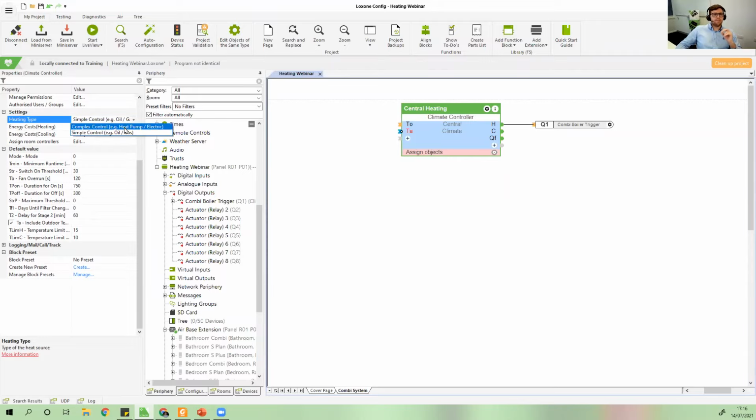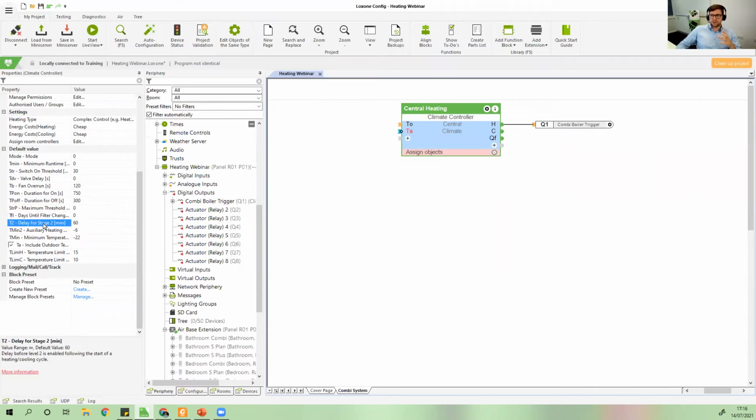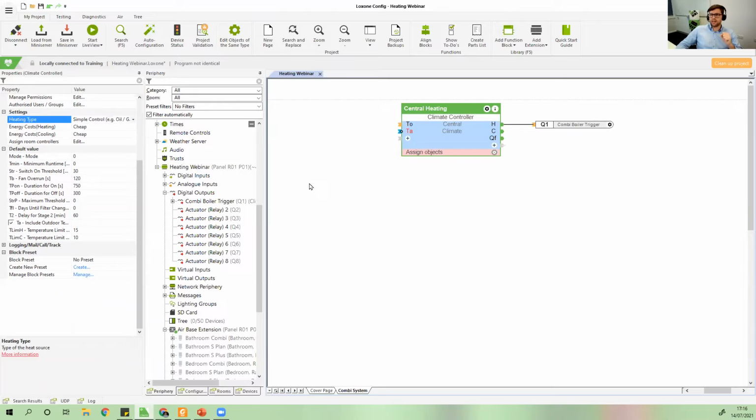The reason is the heat pump electric option includes things like minimum outdoor temperature and sequencing and threshold and filter times. Now, this is really only relevant towards large HVAC systems or heat pumps where you have granular control of them. So not just a heat pump you're turning on and off. So even if you were doing an electric heating system, for instance, an electric underfloor heating mat, I would still be tempted to set oil/gas there, just to get rid of all of those extra parameters.